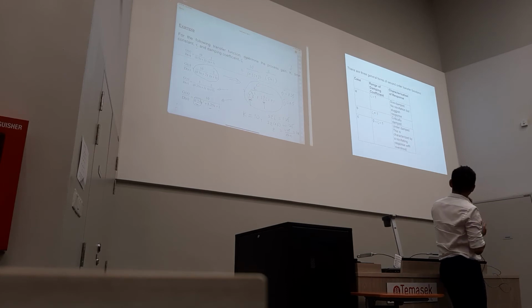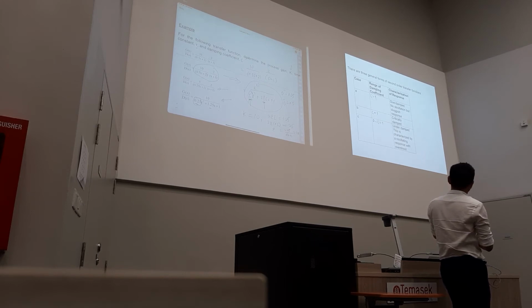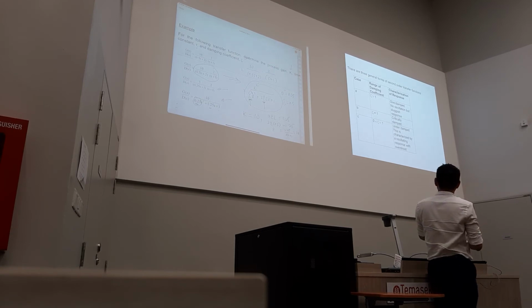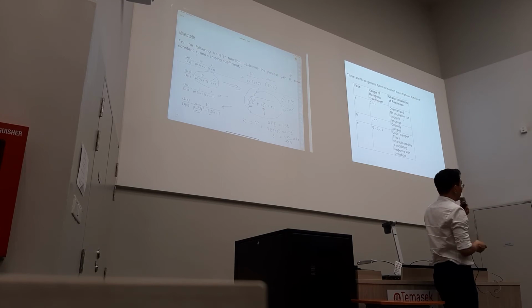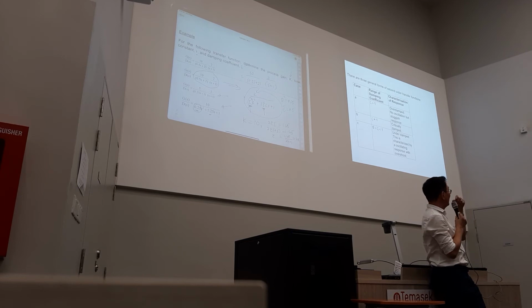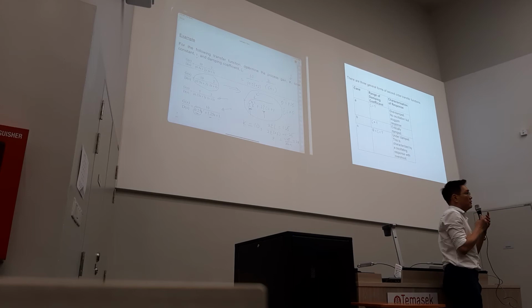Alright, as I mentioned earlier, for the second order we have 3 cases. I have case A, case B, and case C, 3 cases. And the range of the damping coefficient for case A is zeta more than 1. More than 1 means 2, 3, 4, 5. So any zeta that is more than 1, we call it overdamped. No oscillations, but it's a sluggish response, which means that if I arrange my second order into that format and I realize the damping coefficient is very big, my process dynamic is very slow.